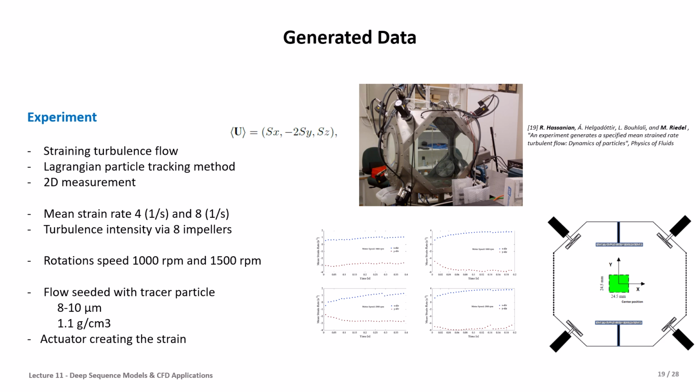But how are we measuring the properties of the flow? This is based on particle tracking in fluid dynamics experiments. With this approach we can see the flow with a particle, and then track this particle with a laser light and detection system. Then we can track each particle's motion, giving us its displacement and velocity, and we can calculate the acceleration also.